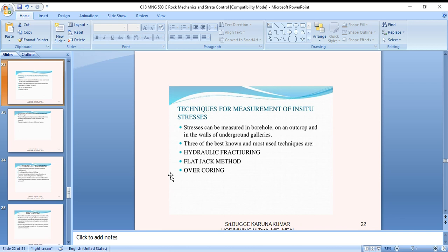Surveying instruments have also been used for measuring comparatively small lateral and vertical displacements over the mine area. Prior to failure, this displacement may be on the order of fractions of an inch, and accurate leveling, chaining and triangulation measurements are required. Similarly, in the underground,